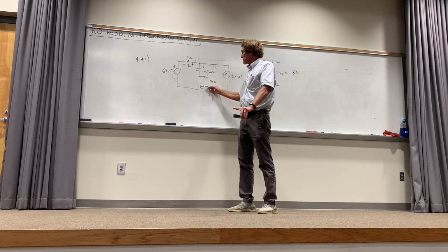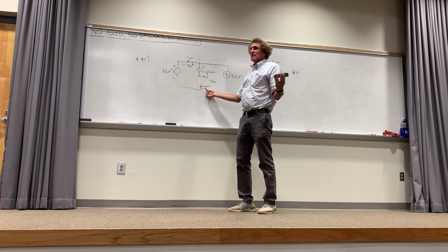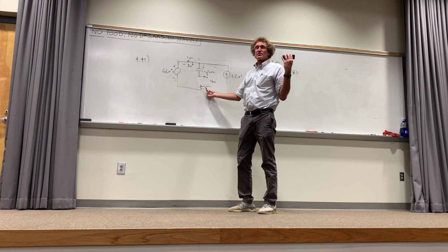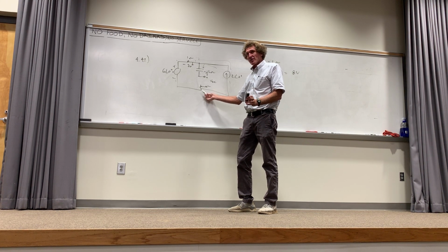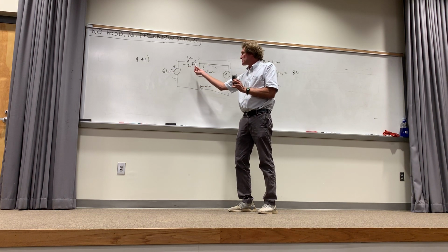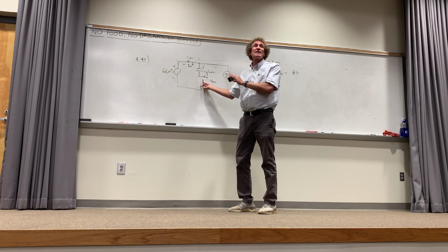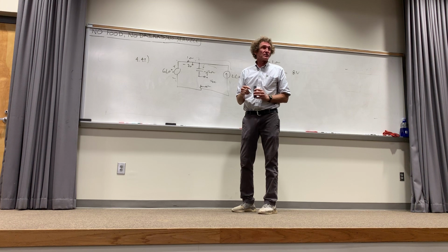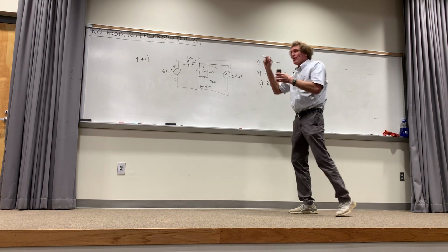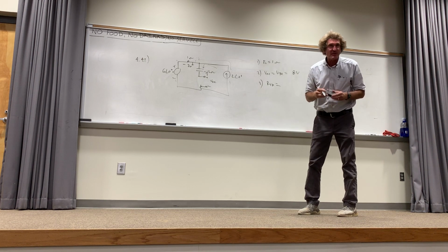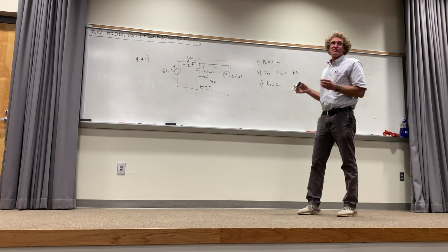All right? I always say, and this is the easiest way, guys, I've been doing this for a long time, taught it many times: start at the negative terminal, find all the voltage drops or increases until you get to the other terminal. That is the voltage between the negative and positive terminals. You all hear me on that one? It's the way to do it. You could set the whole thing equal to 0, and yes, that is in fact what I'm doing, but it's easier, I think, to see.